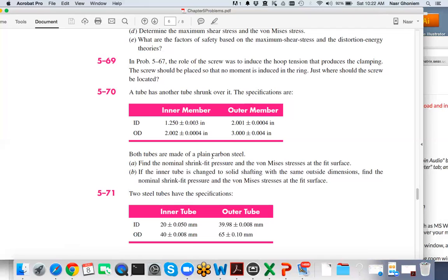One of the common failure theories is the maximum shear stress theory, or the distortion energy. So that's another limit. In other words, this assembly has two limits: an upper limit at very high speed, and a lower limit due to potential yield or fracture at the interface. So you cannot have it both ways. Okay, that's nature.